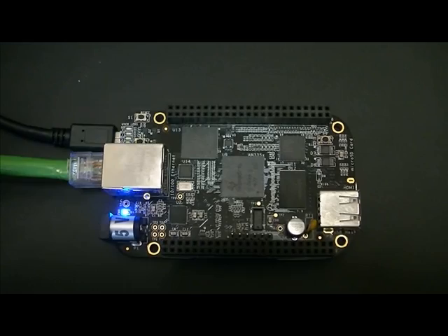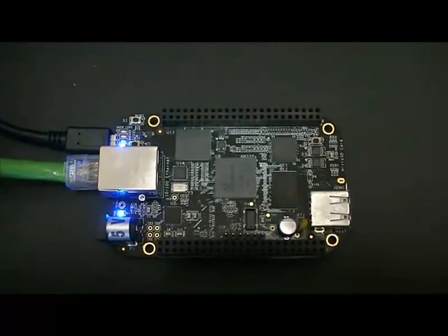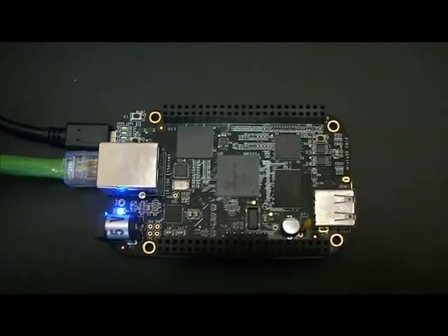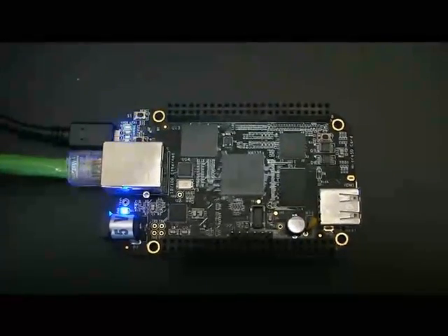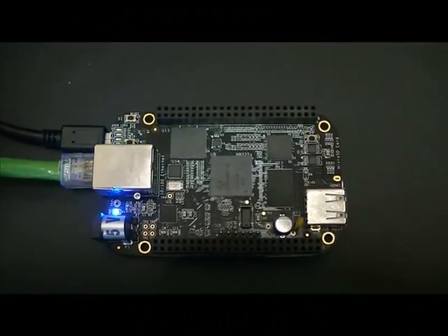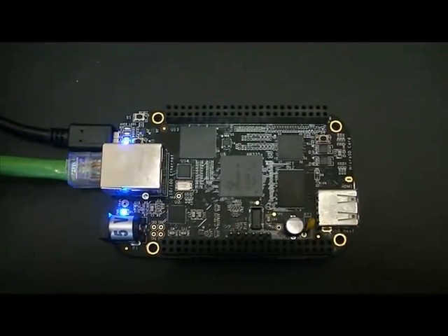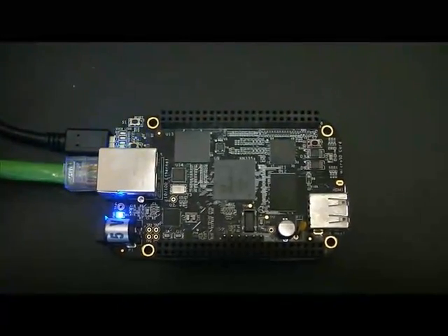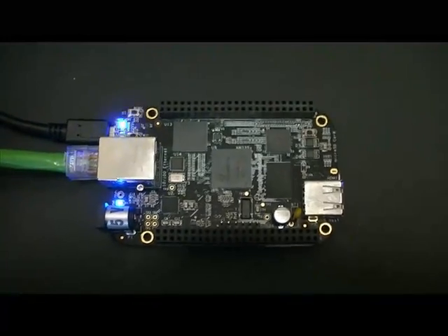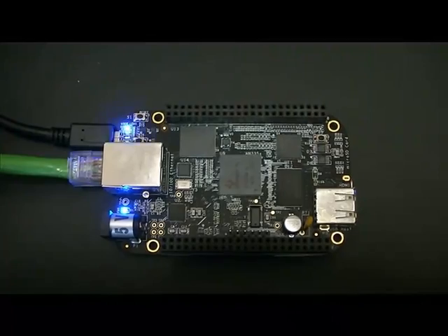For the demonstration, we need, of course, to have a BeagleBone Black board and to connect it to the EICASLab RCP platform. It is connected through a USB connection for powering on the board, and it has an Ethernet connection used for working on the board through a remote terminal and, above all, for the controlled data transfer between the board and the EICASLab RCP platform.